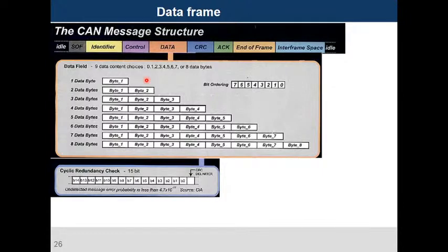You are transmitting data from node A, and the data will be received by node B. How do we ensure that whatever data node A transmitted, node B received the same? Here the CRC is the key. The CRC data is calculated on node A and evaluated on node B, so we can verify that what is received on node B is the same as node A transmitted.